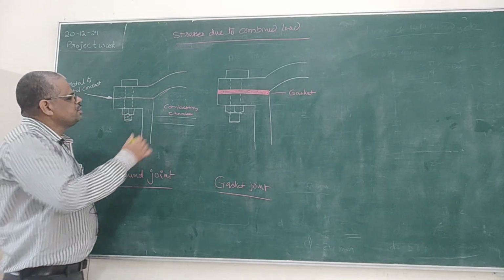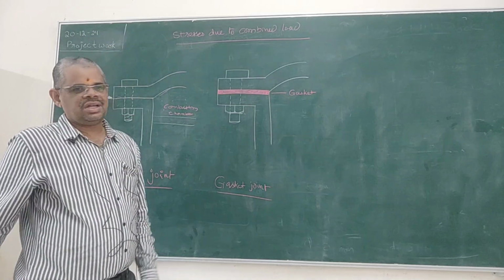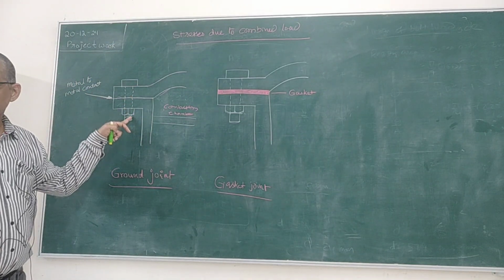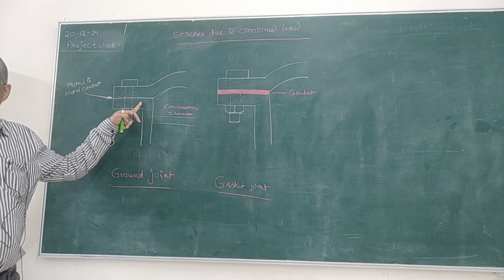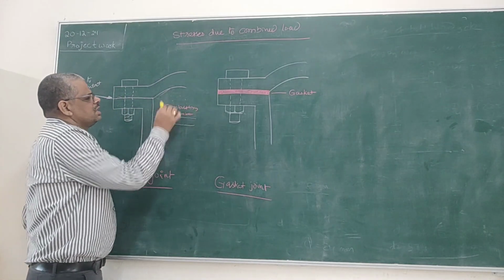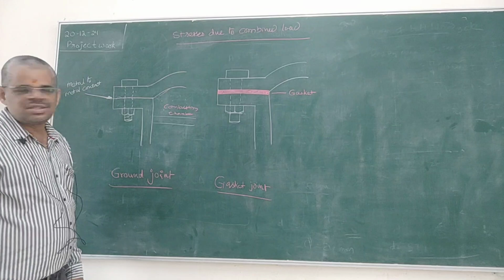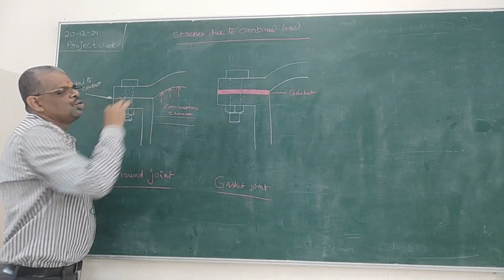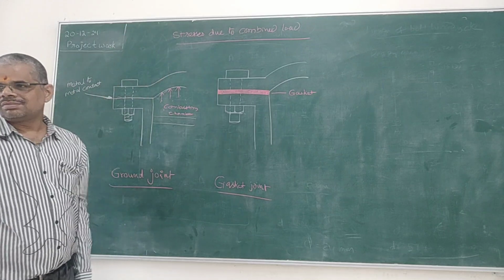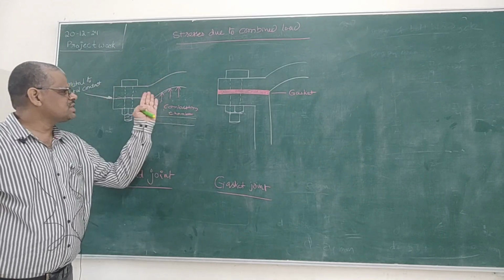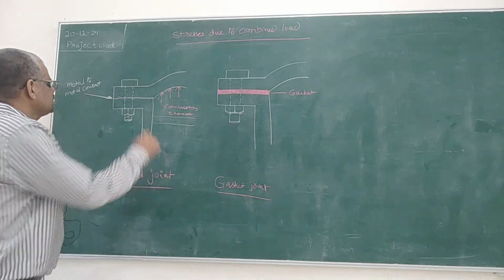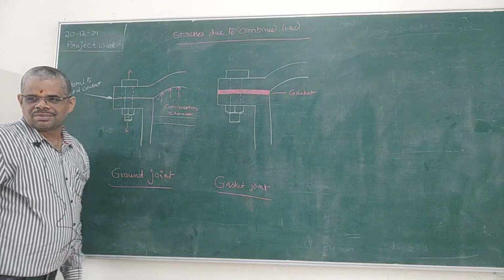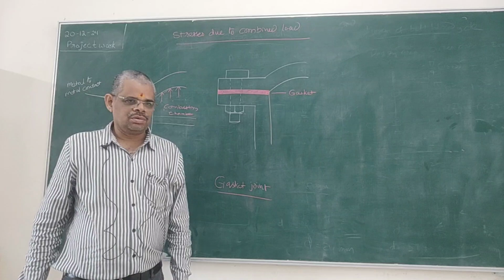And also during the process of combustion, this bolt is already subjected to initial load. So it is under tension already due to initial load, and at the same time the combustion is taking place. Due to this combustion, these combustion gases will try to move the cover upwards because of their pressure. So some force is acting upward. That means this bolt is also subjected to tensile load.